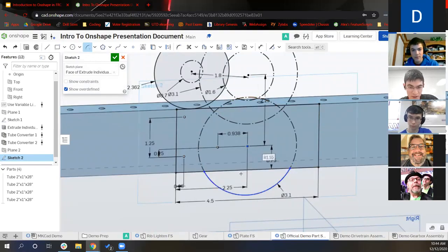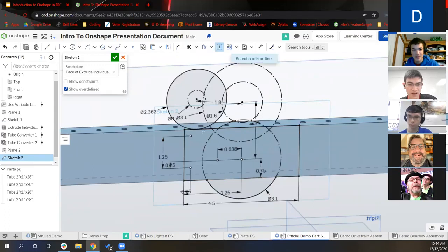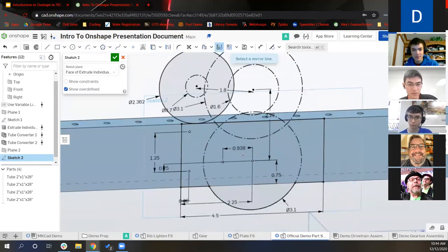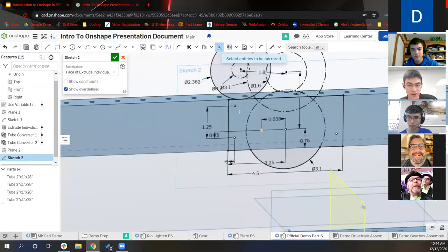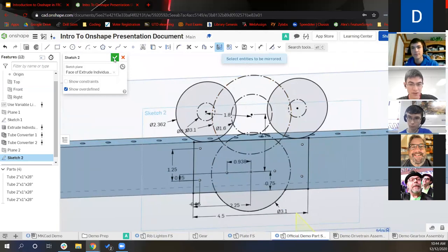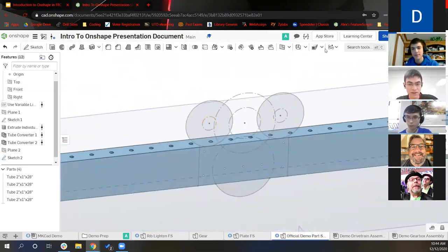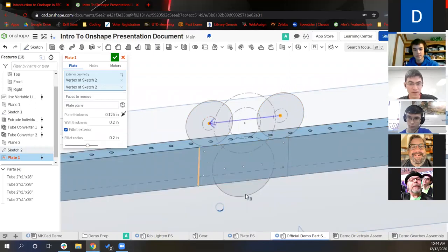We're designing this gearbox in such a way that it covers the gear in the bottom here. That's why that arc is being drawn and some other things. It'll make a little more sense once we use the plate feature script. But basically in this sketch, we're just laying out what the gearbox looks like from a layout perspective. So we're defining those points there that Alex is working on right now. Those are what's going to interface with the drive tube. Those are the places where bolts are going to go through and actually bolt this gearbox to that drive tube. And then all these other circles and things are just so that we know where to put the bearings and things, so that when we put the gears in the gearbox, everything will interface and mesh nicely.